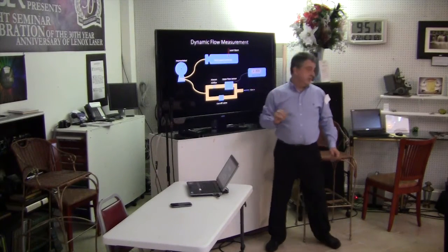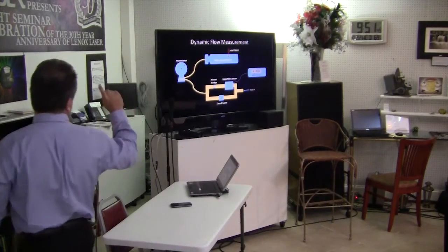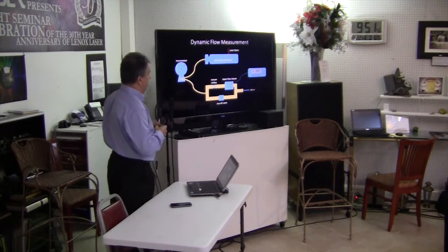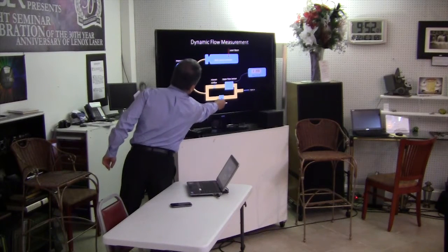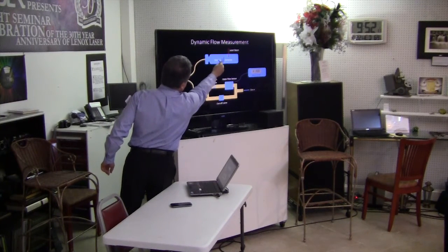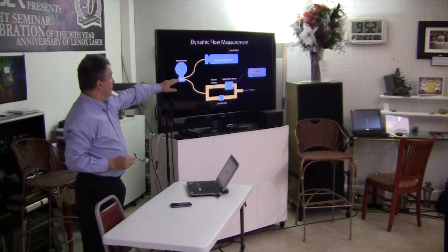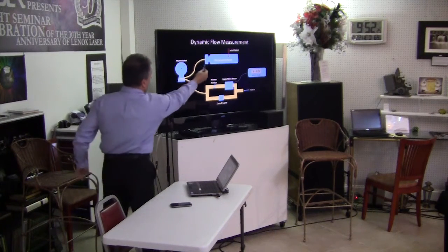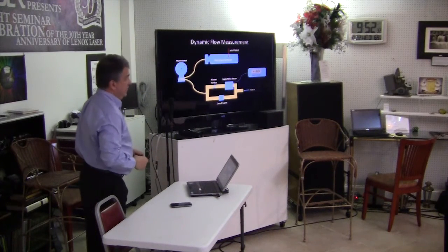And then you look at the manometer and you look for the steady state. So in other words, I'm not blocking anything, am I? Okay, I'll move to the other side. You look at the manometer and you watch that needle not to move. So that's step number one. That means that everything is pressurized exactly the same. Then you close one of those branches over there, and there is your calibrated orifice. And you start drilling there, start creating the leak there, and the mass flow sensor will see any change. If there is no hole there, there is no flow in the gas, there's no pressure differential. Once you start creating a leak, the gas will start flowing through the mass flow sensor, and it will measure that particular flow.